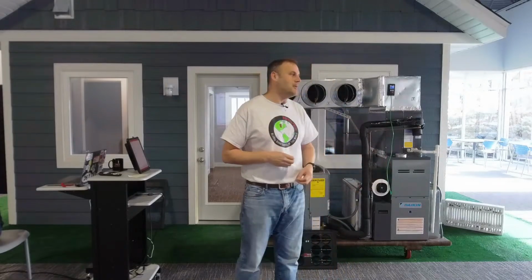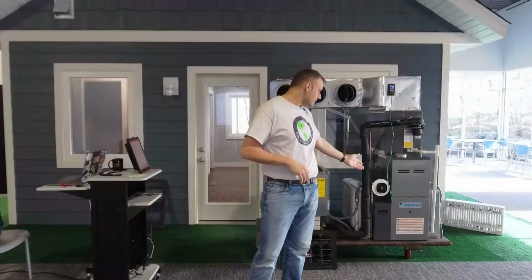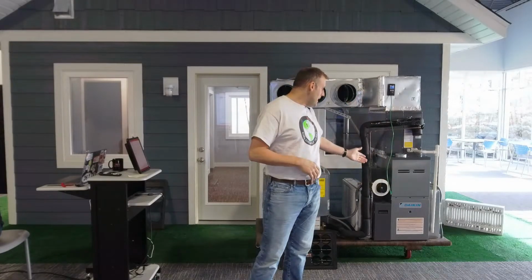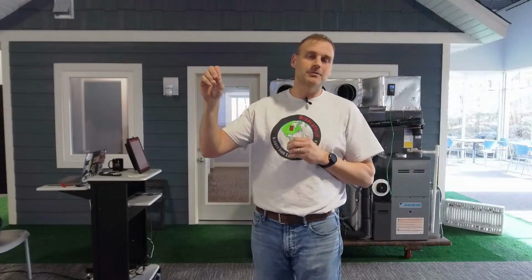They handshake, they go hand in hand. Flipping the script, going to heating mode, heating is all sensible, but I want to set the airflow right on that furnace because I don't want a cracked heat exchanger that's going to come sooner than it needs to. I don't want to kill a fan motor, so I'm also watching pressure. I didn't quite get into this yet, but the tool measures total system airflow. It's also benchmarking pressures as we go through the workflow.